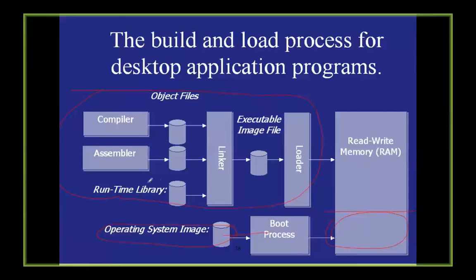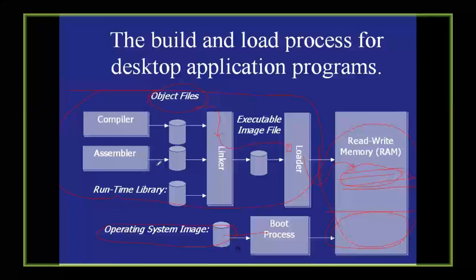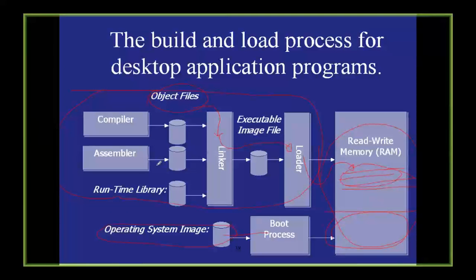This is your entire IDE-based process, which we spoke about. The IDE will have some compiler, assembler, and libraries, and they will convert the source code to object code. Object code gets connected to the linker, and then the linker creates an executable, and this exe gets loaded using a locator. So you map this application virtually, or even physically by linker scripts, to a specific area in the RAM, and then your application runs as long as your machine is up, doing the same job again and again. So that's a strategy for desktop development.